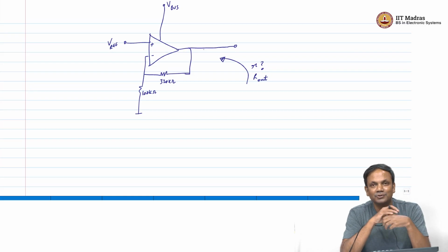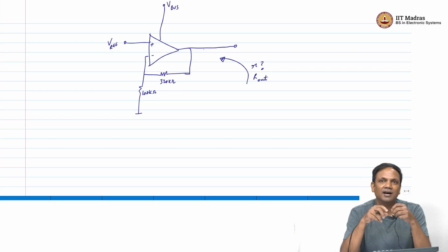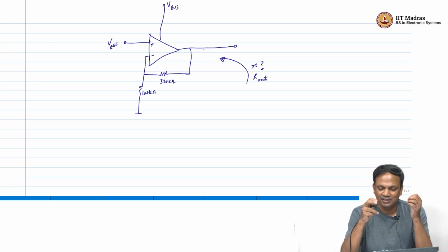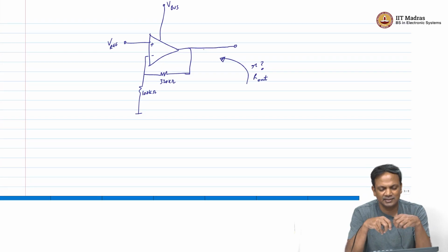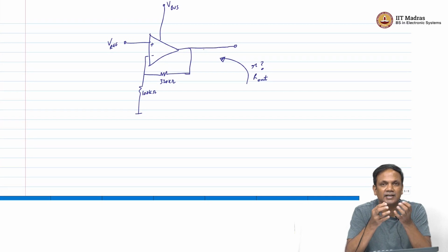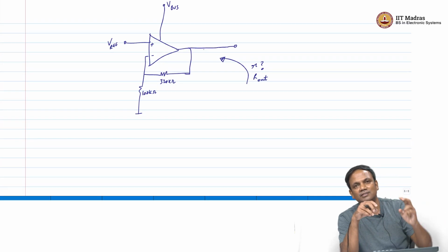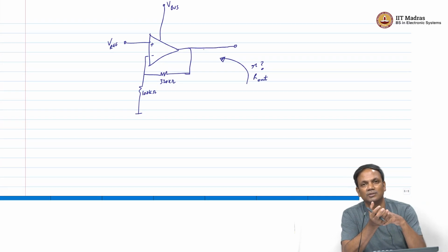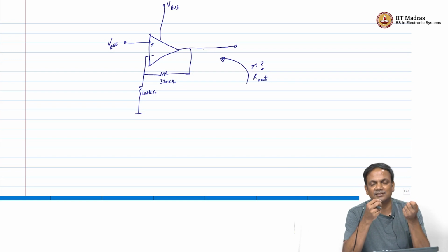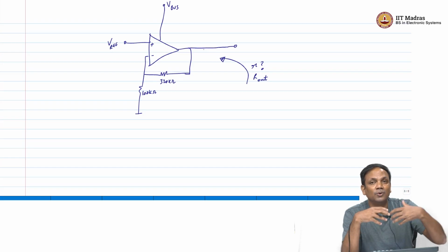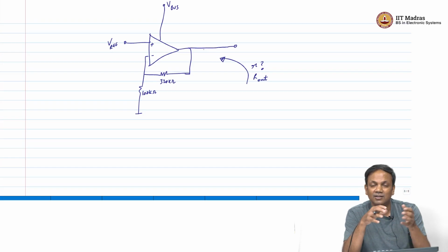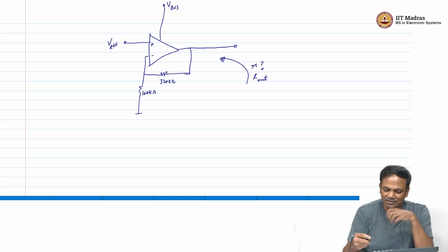So, what contributes to the R out? What actually contributes to the R out are physical things like wires. You might have seen this with batteries. When you look at the battery, there will typically be 2 leads from the battery that connect to the PCB. Those leads have resistance. The battery also has resistance. Any routing that you do after your feedback circuit to the battery will also have resistance.